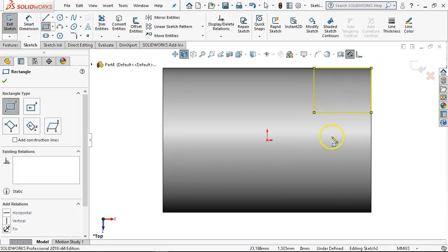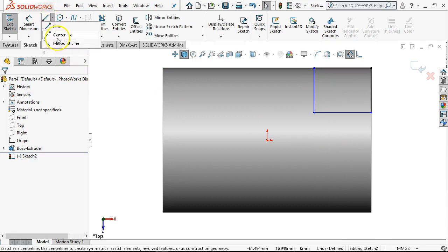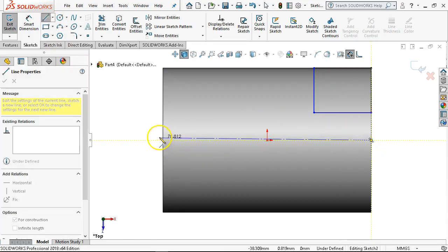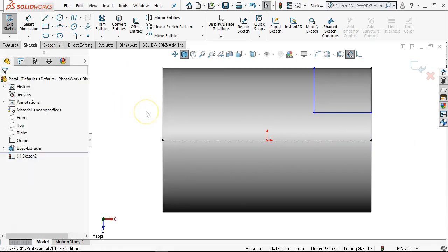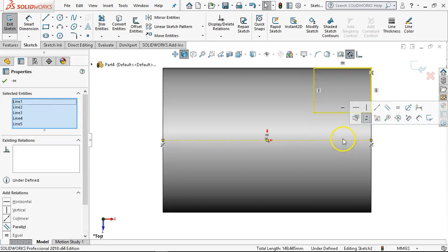All right, so we're going to have some symmetry here with the notch cutouts. Now, manufacturing this, I kind of look at it as if I'm holding onto this bar and put it in a rotary, I'm still not going to be able to get to the angle. But if I have it in an indexing collet, I could flip it 90 degrees, run the ends off, and still maybe pick up without re-indicating for this back face. All right, so I'm going in vertically here. So I want to make sure, well, there's an assumption that's on center line, and this one's going all the way through.